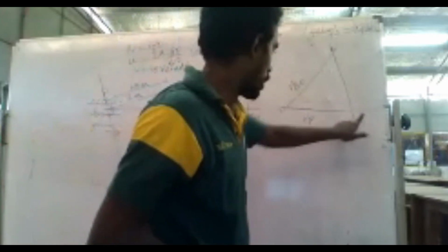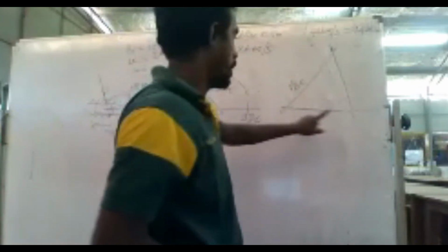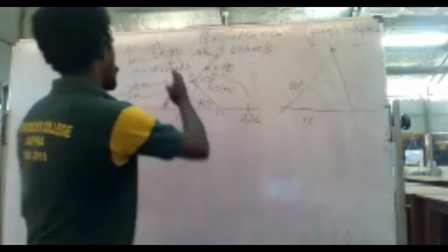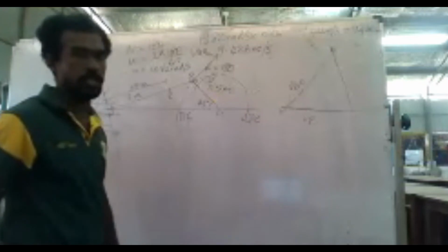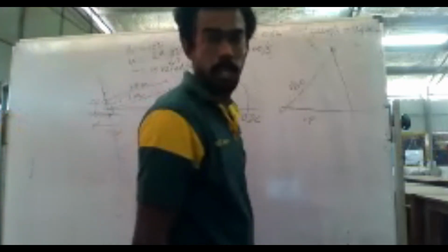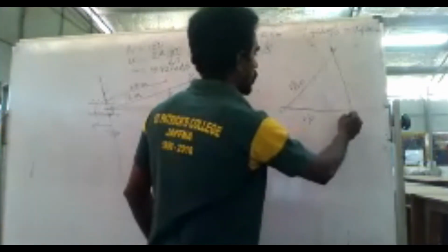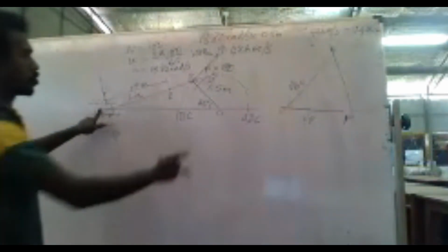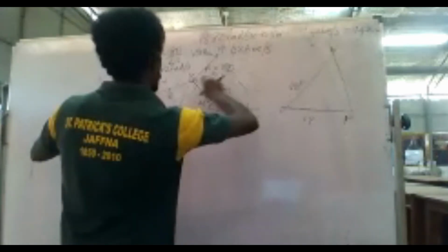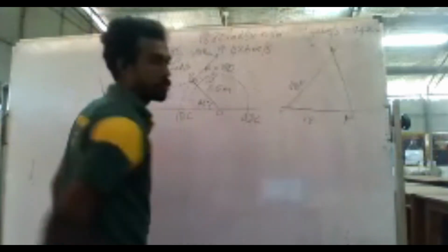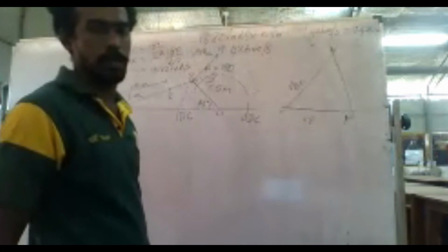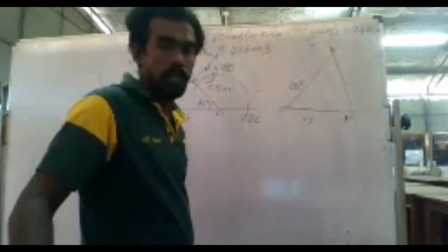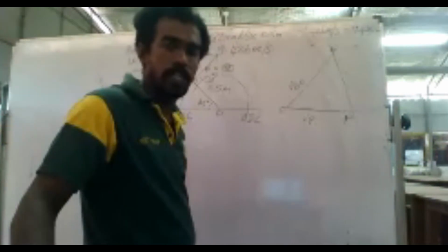So this line of motion of P and this line of motion of the connecting rod, the velocities, they will meet at a point, and that point is our P, right? So my O is there, B is there, P is there. All 3 points are there. So based on this, now we can find the angular velocities and the velocities.